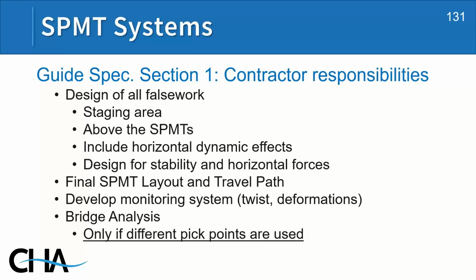We also want the contractor to do the final design of the SPMT layout and to do a final check of the travel path. We also would like the contractor to develop a monitoring system to ensure that the specified twists and deformations are not exceeded.